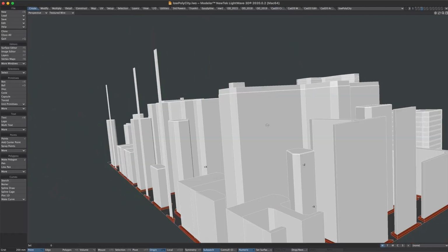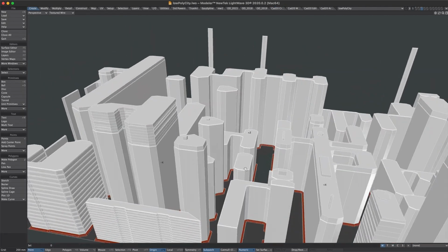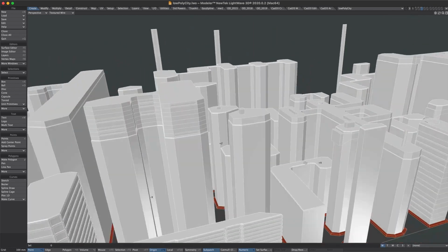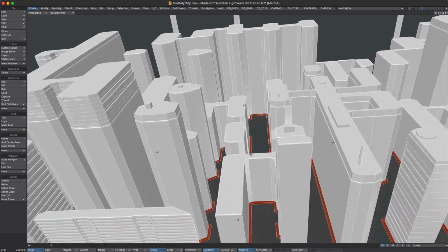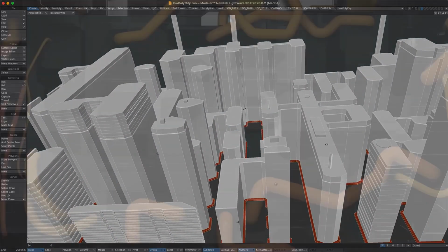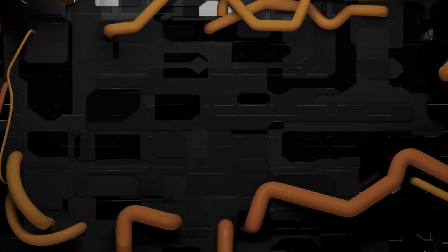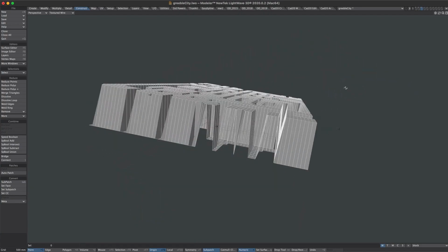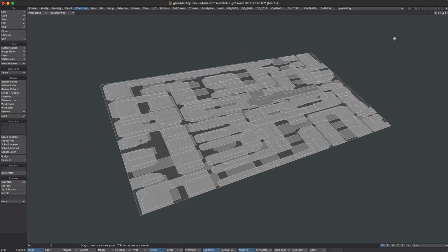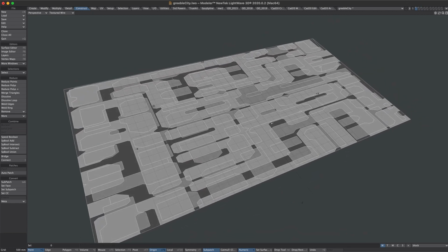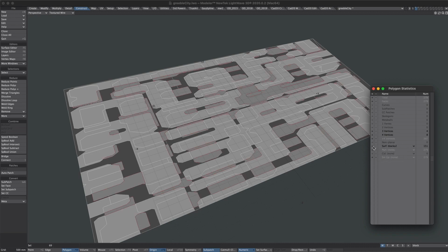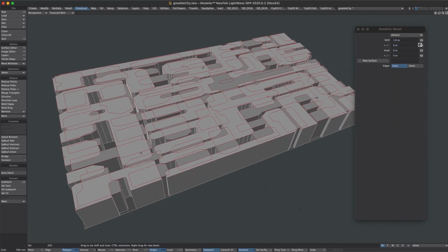I applied the exact same method to come up with a little city block as well. So it's a very versatile technique and it'll help you come up with shapes you wouldn't necessarily have thought of yourselves. A quick note on the render I made for the poster frame. I actually used 2 cutters on this one, just varied the parameters slightly for each, which gave me this. And as before, I just selected the cutter object surfaces and did a simple bevel, as I showed earlier.